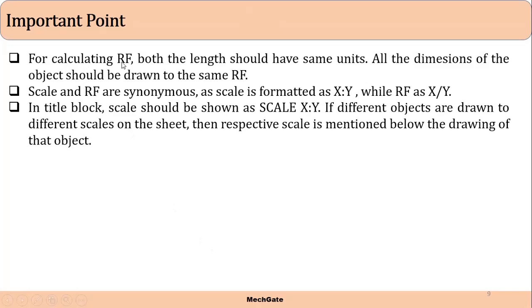For calculating RF, both lengths should have the same unit. All the dimensions of the object should be drawn to the same RF. So while preparing the drawing, all the length units of the object should be prepared with the same RF, right?